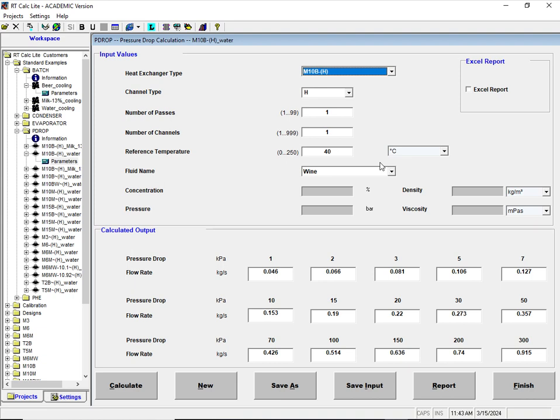If you're a guy at university, you know exactly what I mean by non-linear. The heat transfer equations themselves, if you look at the log mean temperature difference, are non-linear. The stream calculations, MCp, m dot Cp delta T, those are linear. But when you get to the log mean temperature difference part, it's non-linear. So the heat transfer itself is non-linear. You know, U A F delta T log mean. The whole equation is non-linear. Then when you look at the heat transfer coefficients themselves, they are highly non-linear. They've got power terms and all kinds of things.